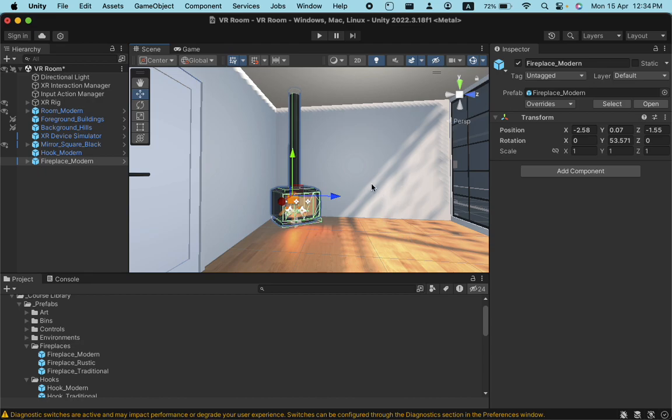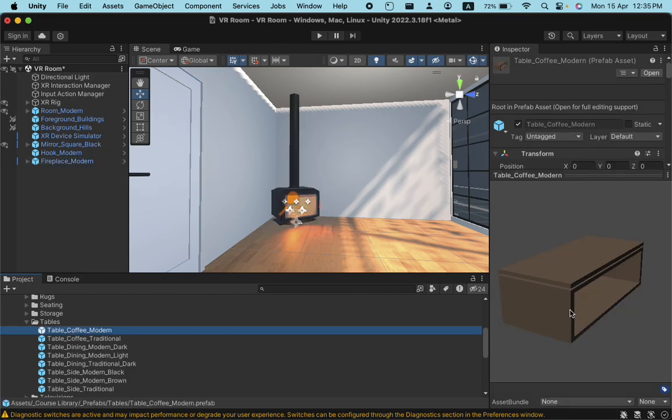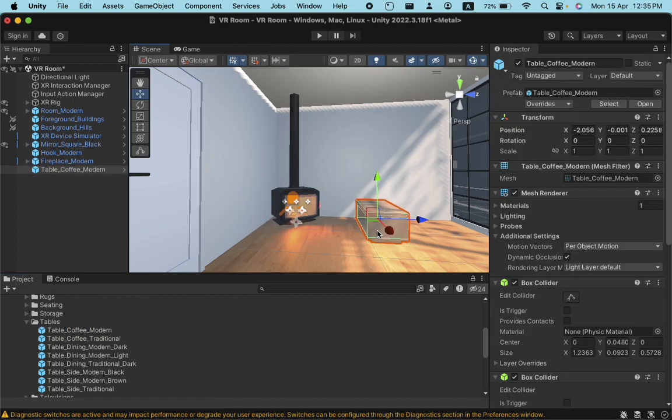And then let's place a table here and a TV over that, and then you do the remaining. Tables. Yeah, so let's place this table. Okay, so one way is actually rotating it. Another simple way is you just type the rotation angle here. Let's say 90 degrees. It can be 90 or minus 90.